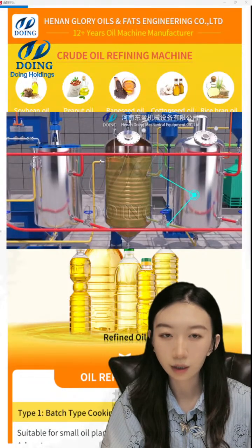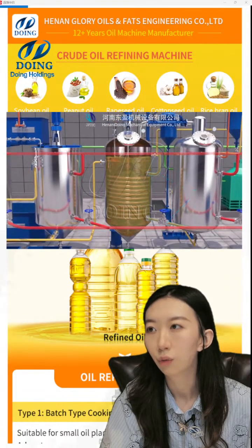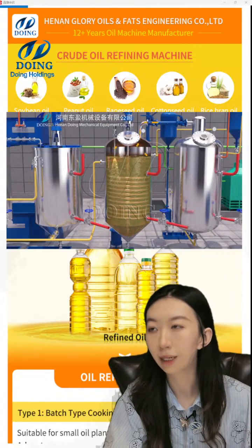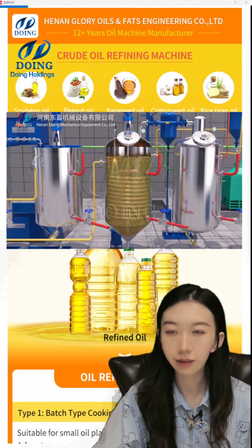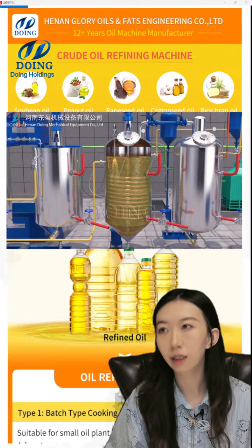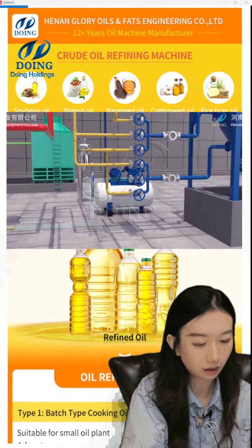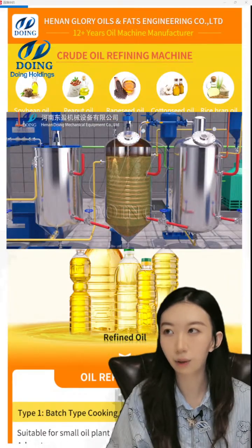Before the decolorization process, we heat the crude oil to remove internal moisture, and then we add active clay as the decolorization absorbent. The active clay is equivalent to 1% to 3% of the oil weight.